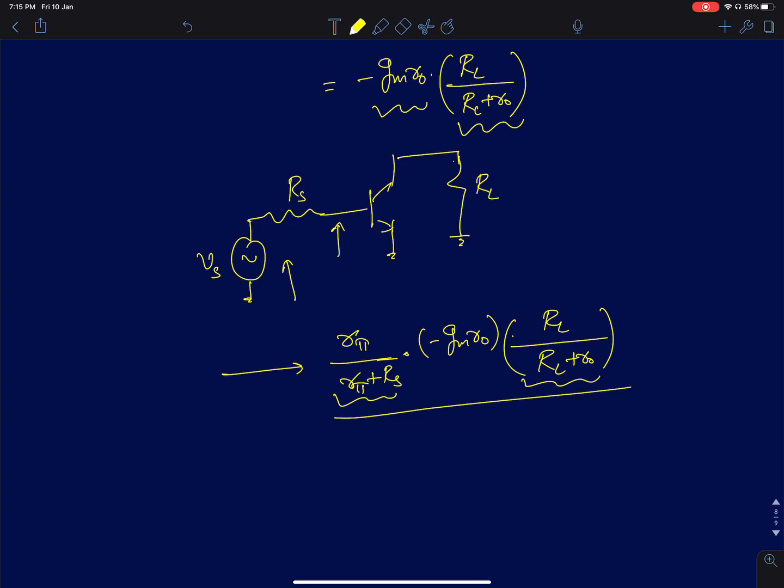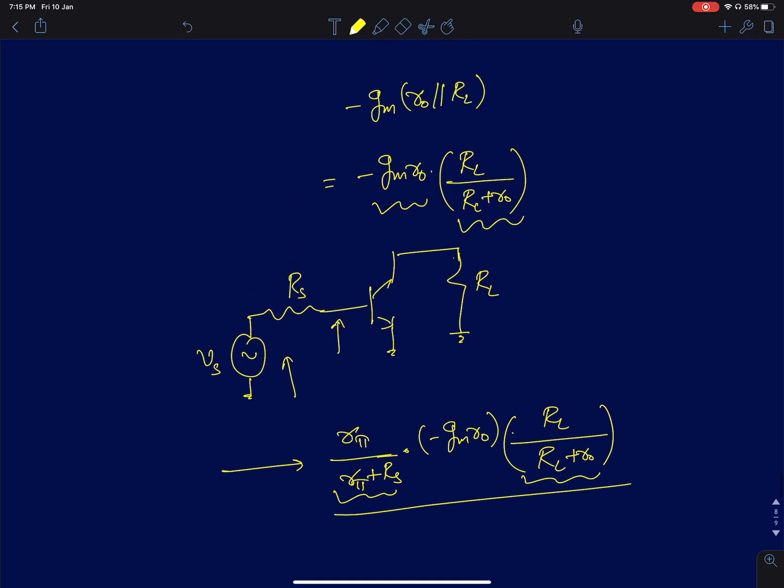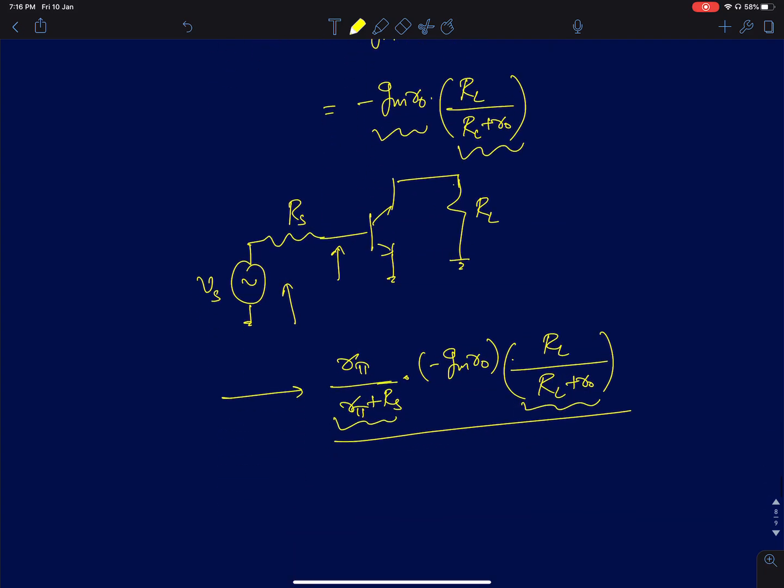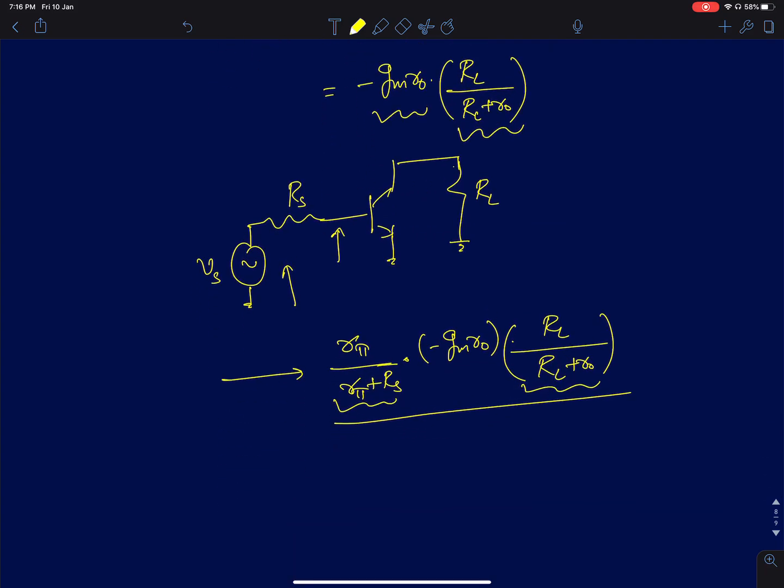Okay, so this is all about the common source configuration. As I said, this is more of an introductory video on common source. As we proceed, if it's too trivial for some of you, you can skip these videos, and I'll quickly go to the frequency response. But the intrinsic gain test setup is pretty useful, especially before you start amplifier design. I normally do that, so that it gives me an idea as to what the fundamental gains are for different device lengths, bias currents and W/L ratios. What is the gain that I can expect from this technology, for any given technology?